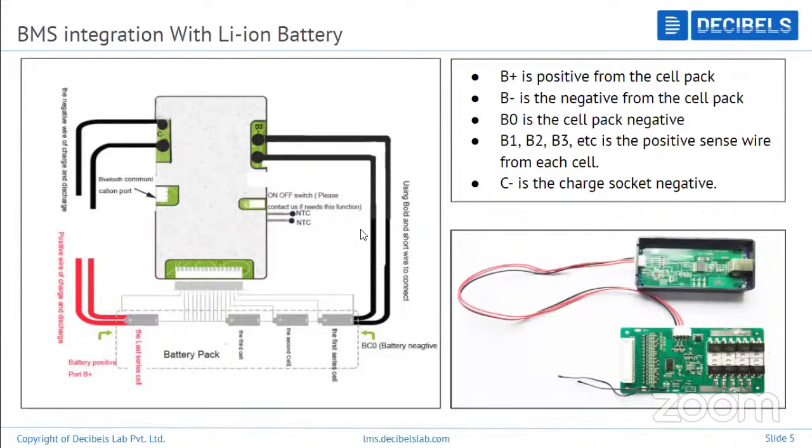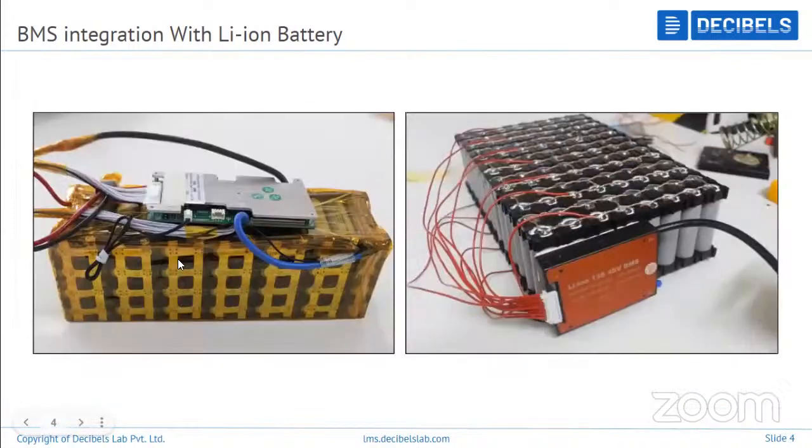So what are the observations which have to be made while integrating? I'll just have a few points on that. You could see there are bold and thick wires used for the discharge current, at the end of the discharge, right? You have bold and thick wire here, and right here. Why is it? It depends on current carrying capacity. The wire has to have the capacity to carry such a high current. So it's based on the current carrying capacity; the gauge and thickness of the wire matter. So thick gauge wires and multi-strands are used to withstand 30 amps and more, right?